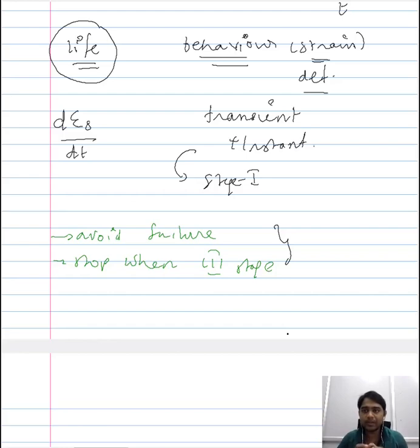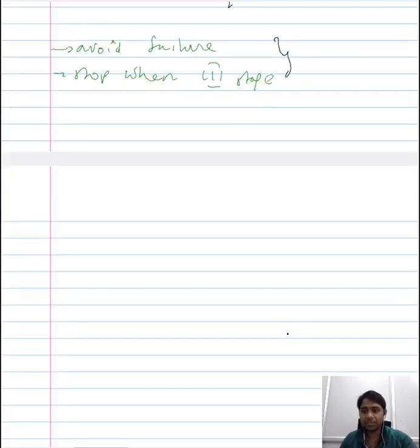Now, there are similar tests that you could perform when you want to focus on the time that is required for the material to fail. So when you want to largely focus on understanding the failure of the material at high temperature, then you can perform a similar test. However, the creep test will not be super suitable for it, because when we described the creep test, we talked about one of the factors that should be maintained constant, which is the constant stress.